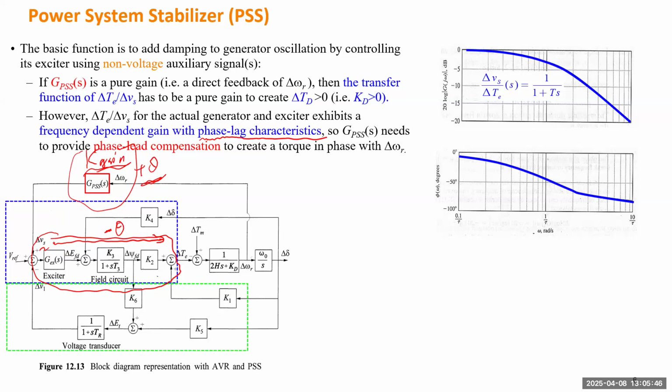If we draw the Bode diagram, the first one is for the amplitude. It tells you the amplitude will be decaying when you increase the frequency. At steady state, it doesn't change anything. At steady state, the amplitude is 0, which, because this is logarithmic, means it doesn't change the signal. But when you go to high frequency, the value will decrease. So this is like a low pass filter.